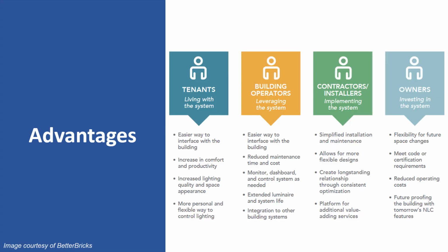Overall, by embedding sensors and control functionality into each luminaire, control is highly granular and responsive, which can result in improved energy savings. For the electrical contractor, luminaire-level lighting controls can ensure control compatibility, simplify wiring, and reduce time and risk by eliminating installation of control devices. Functional testing typically becomes the responsibility of the contractor as opposed to an additional party. For the electrical distributor, it offers an energy-saving solution that can streamline product schedules for lighting projects.